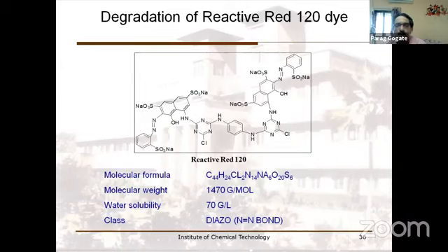In ballast water treatment, it definitely has to be a single pass, because you can't keep on recirculating the water due to very high volumes. I really can't recirculate it for a number of passes. So single pass is a key requirement there, and then there were some problems in that. But yes, seawater disinfection was shown to be quite successful, and there you can use hydrodynamic cavitation.